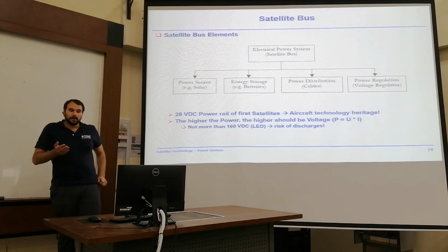But in general, for the regulated bus technology, you could use a 3-domain controlled regulated bus. That means that the regulated bus voltage is controlled either via the sequential switching shunt regulator, the S3R, a battery charge regulator, BCR, or a battery discharge regulator, BDR.